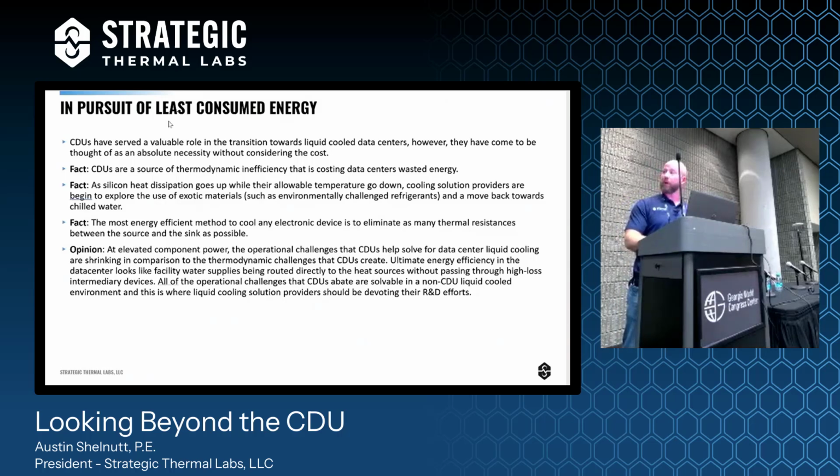The final one on here is my opinion. At elevated component power, the operational challenges that CDUs help solve for data center liquid cooling are shrinking in comparison to the thermodynamic challenge that CDUs create. Ultimate energy efficiency in the data center looks like facility water supplies being routed directly to the heat source without passing through high-loss intermediary devices. All the operational challenges that CDUs abate are solvable in a non-CDU liquid-cooled environment, and that is where liquid cooling solution providers should be devoting their R&D efforts.